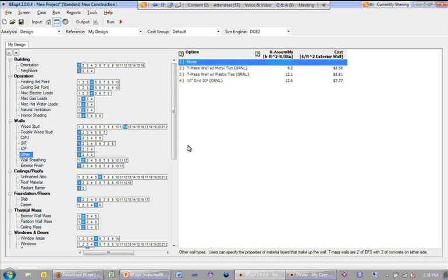Great, thank you. I was trying to see if there's a way to model an economizer in this, and it looks like on your HVAC areas, it's probably not an option. Would there be a way to do that under the whole house fan option, or anything else you could think of along that line? Well, we currently don't have a whole house fan option. That's something that we've been working on adding. I might recommend using a natural ventilation option.